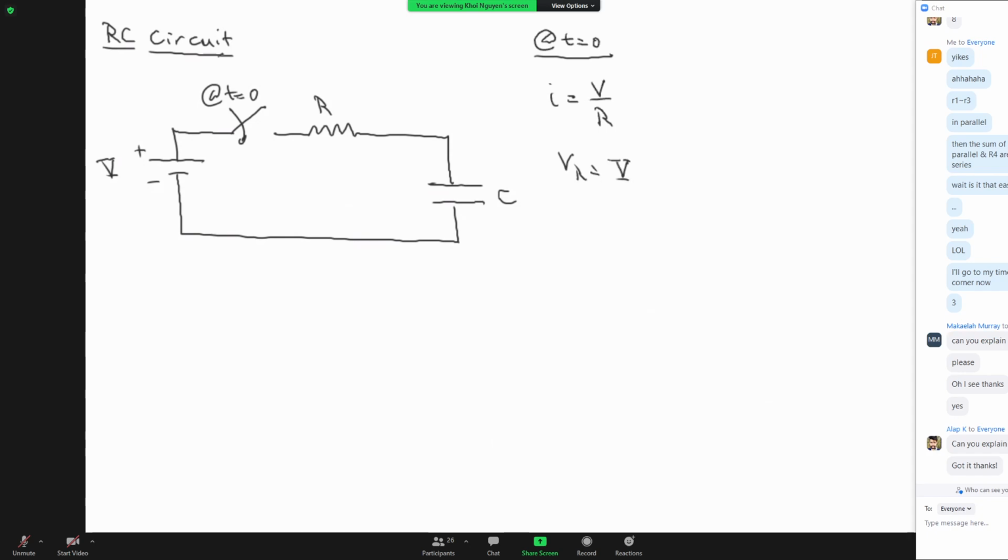capacitors have what we call electric flux, and initially it has 0 electric flux. So even when the circuit is closed, it'll still have 0 electric flux at that specific point in time, which means it can't build up any charges on there, which means the voltage across the capacitor is 0 when we first start. This has to do with electric flux.